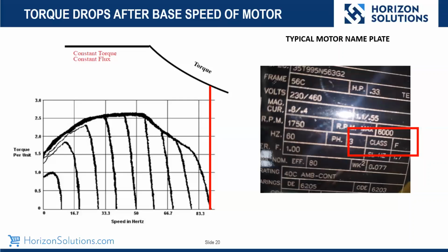That basically is the limit where the torque drops off with a Tesla design motor at 90 hertz, and then you're in some serious problems because you've gained it all in RPM and you've lost it all in torque. So all the physical and mechanical attributes of the motor definitely hold true here. So be very, very careful. It's very important when you overspeed to make sure that you have enough torque. Next slide.